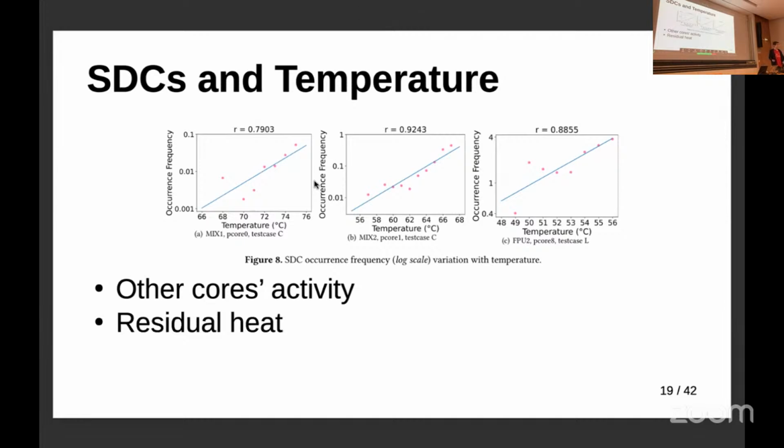Another example included the order in which testing would run could affect the SDC rate because some test cases cause the CPU to get warmer than other ones. So if a test case which generated less heat was run before a test which found an error, then it would be less likely that the second test would find something if the CPU weren't preheated by the test case which causes it to get warm. Also, they found that optimizations to their testing framework itself could cause the CPU to generate less heat and in fact cause the test cases to detect fewer errors, even though the test cases themselves were unchanged.